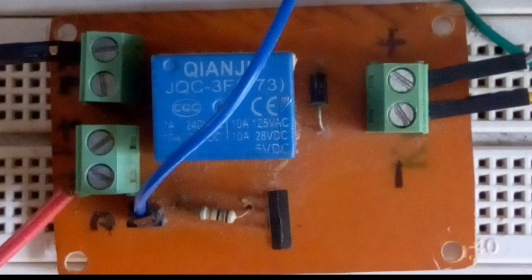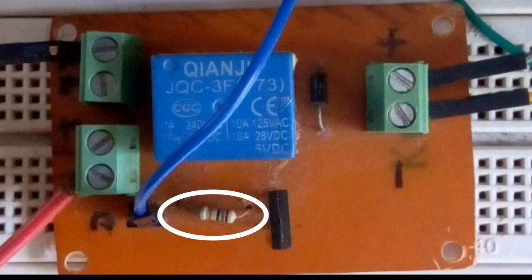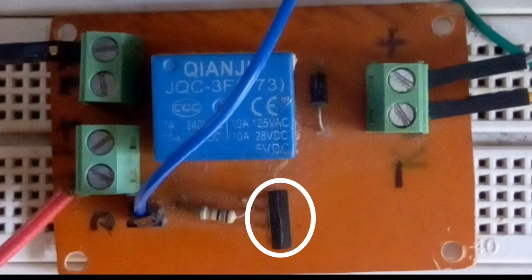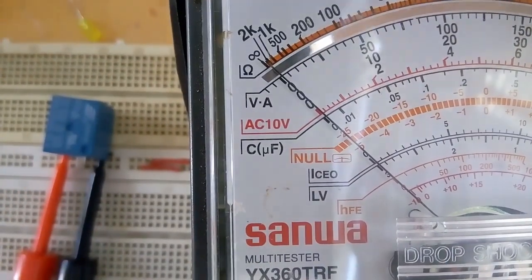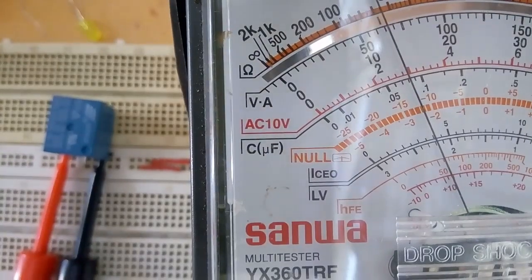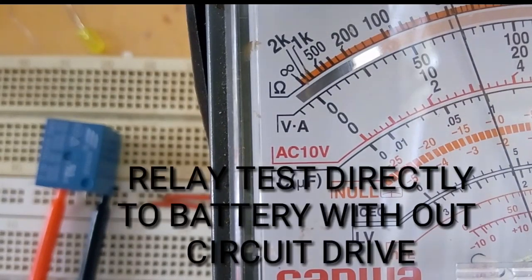As you can see, my driver relay switch circuit components: the relay switch, the 10K ohm resistor, BD139 transistor, and the rectifier diode to protect the transistor. Now, let's test the relay switch circuit by using an analog tester. You can see the current is 75 milliamp, which is connected directly to the battery or the power supply.